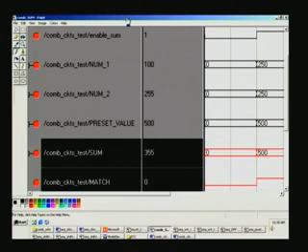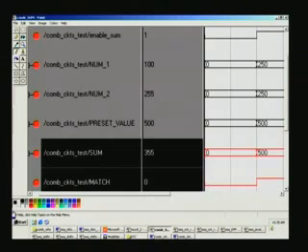Shouldn't I make it like if the enable sum is low, the output should be in a high impedance state or something? It is, this is one such example. Depending upon your actual circuit requirement, you will be designing. You can do that way also, right? So you had used a mux there. So instead of putting 0 there, you can say z there. So a tri-state will appear there. Or you want x there, you can get that. Or any other data that you want to output at that point of time, when that thing is satisfied, you can always put there, right?